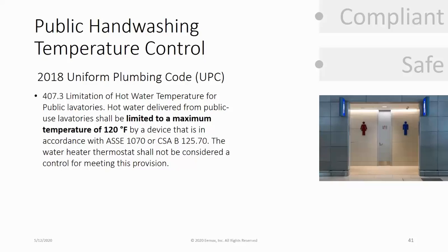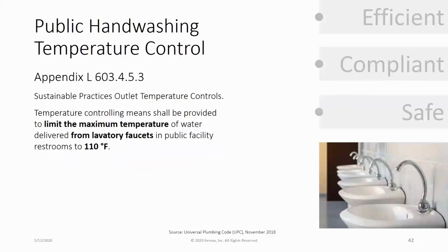A couple slides ago, we talked about ASSE mentioning anything above 120 degrees is a potential hazard. Therefore, they came out with the appendix, which dropped the maximum temperature down to 110 degrees. That temperature still had to be regulated through the mixing valve.